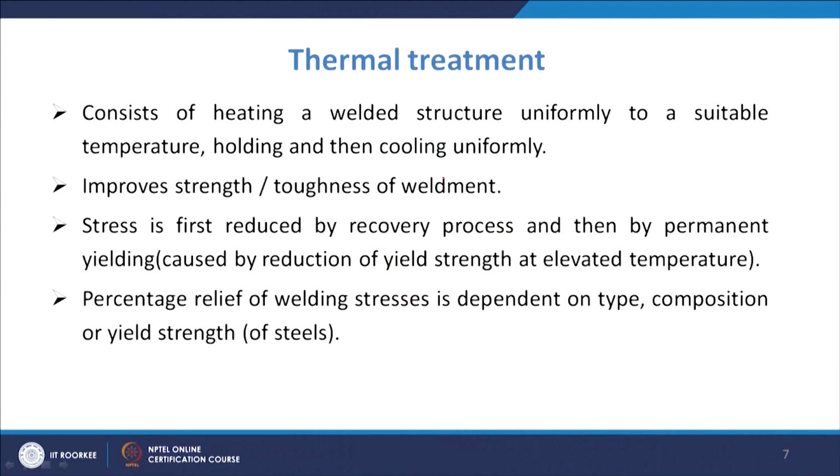You have another method, that is thermal treatment. By thermal treatment you are subjecting the material to heating and cooling in a certain fashion, so that the stress is relieved.